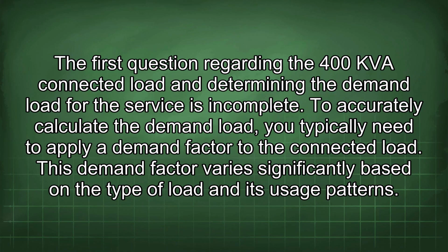The first question regarding the 400 kVA connected load and determining the demand load for the service is incomplete. To accurately calculate the demand load, you typically need to apply a demand factor to the connected load. This demand factor varies significantly based on the type of load and its usage patterns.